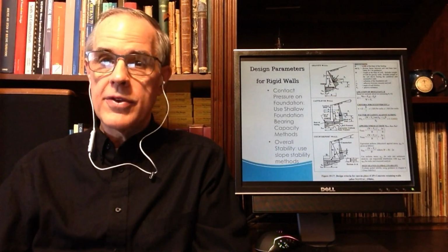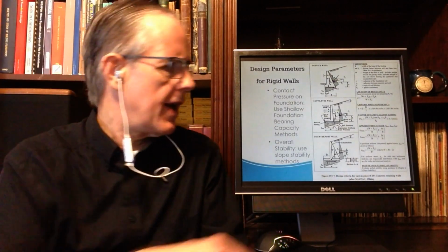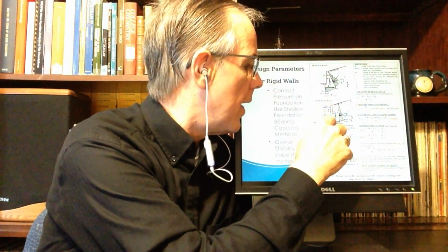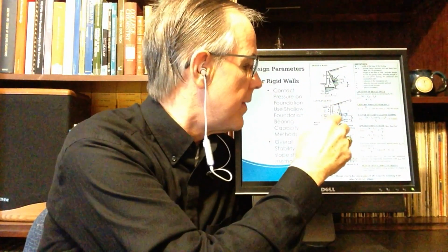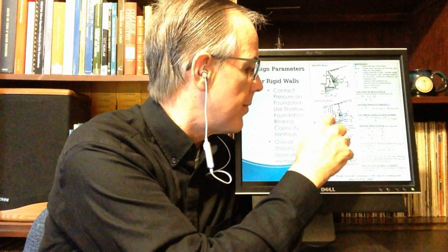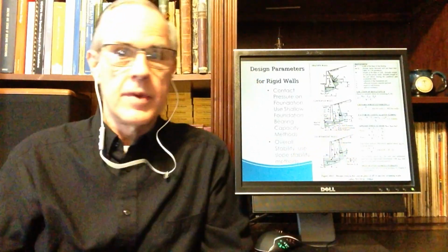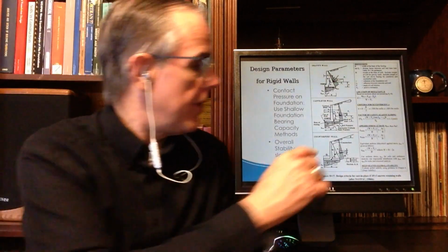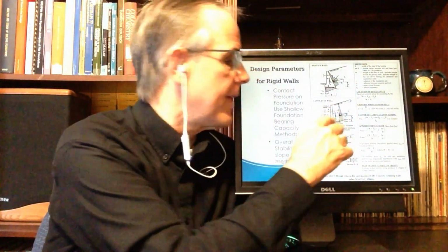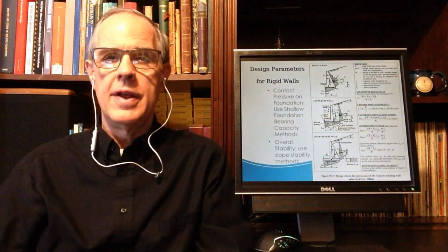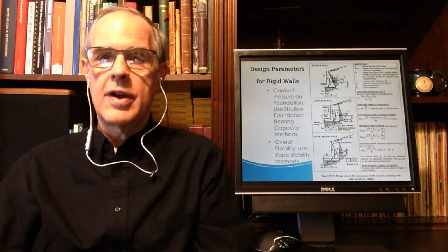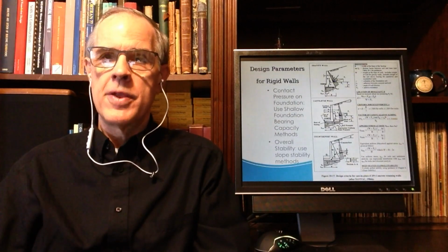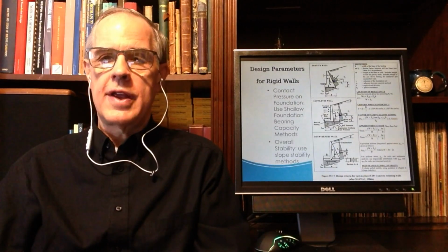There are some downsides to doing that. The biggest downside is that we significantly reduce the moment of inertia of the concrete, which creates bending and internal stability problems such as breaking down here. As the name implies, this is a cantilever wall, and this acts as a cantilever beam. We're not going to get into that particular part of it, but it's pretty standard concrete design. We don't normally like to do fancy stuff for most geotech applications.